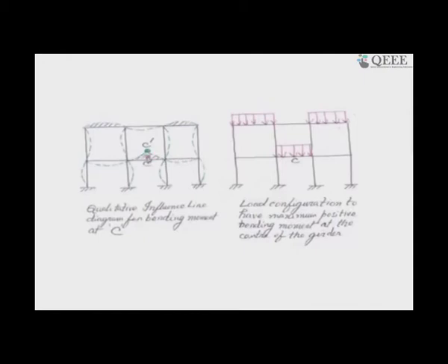Suppose my hand is not both ways, but one way it can release the bending moment. So, if somebody tries to bend my hand this way, he will never be able to do that, because my hand here is already giving way that you can bend it, no problem. Two rigid bodies, one here, another here, connected by an internal hinge, and that is how it will not resist bending moment this way. Of course, the muscles can resist the bending moment, I can become stiff. So, the stiffness can be increased, and if somebody applies load, he will feel some resistance. But without that, with my hand, it is just a release like an internal hinge. So, here an internal hinge is formed.